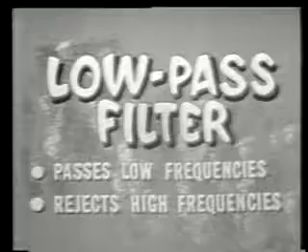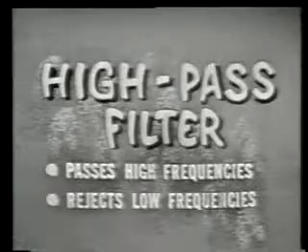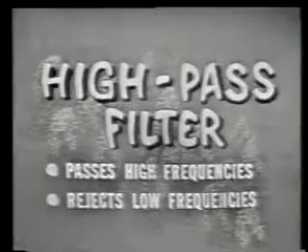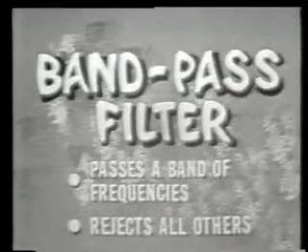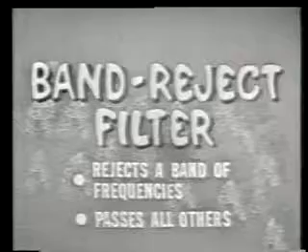Basically, filters are designed to do one of four jobs. One, to pass all frequencies below a specified value and reject all those above that value. Two, to pass all frequencies above a specified value and reject all those below that value. Three, to pass a selected band of frequencies while rejecting all others. And four, to reject a selected band of frequencies while passing all others. All electronic filters fall into one of those four categories, except for a few very specialized cases.